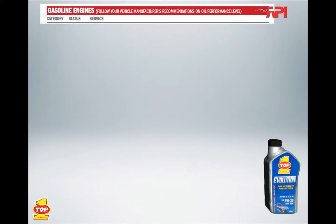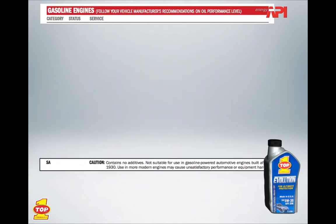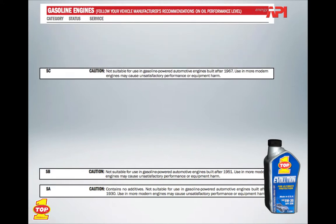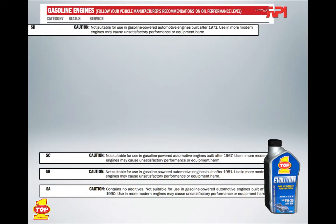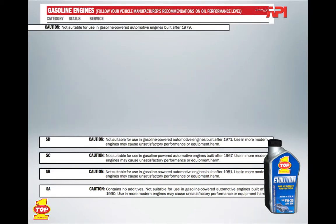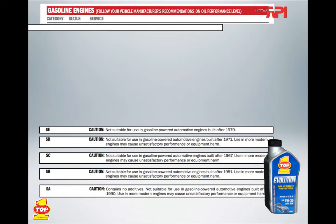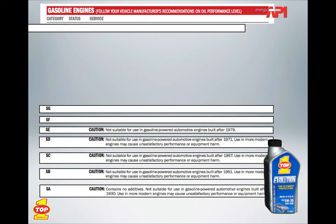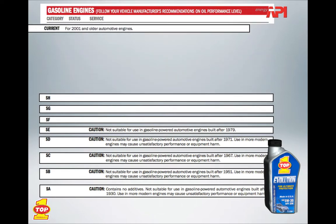The S category is the service category for all gasoline engines. SA was originally issued when API was created in 1930. But as of today, SN is the current S category specification. Here you'll see the S category chart outlining the history of API's gasoline engine specifications.